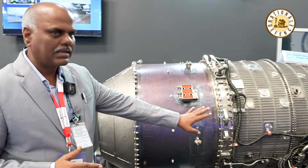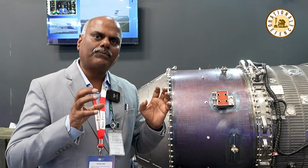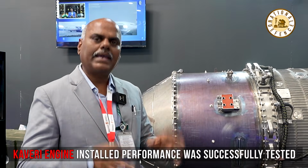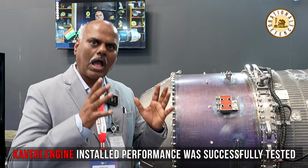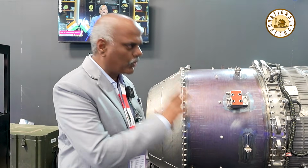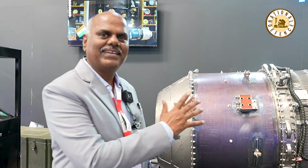Then the engine is tested with aircraft mounted accessories like MAC-B, PTO shaft, aircraft mounted hydraulic pumps, heat exchangers, then JFS. It will be starting with a jet fuel starter. We have done the testing of how the engine is integrated in the aircraft. That is called the installed performance, and we could prove to our ADE that all the performance is doing very well. So this is regarding the Kaveri derivative engine.